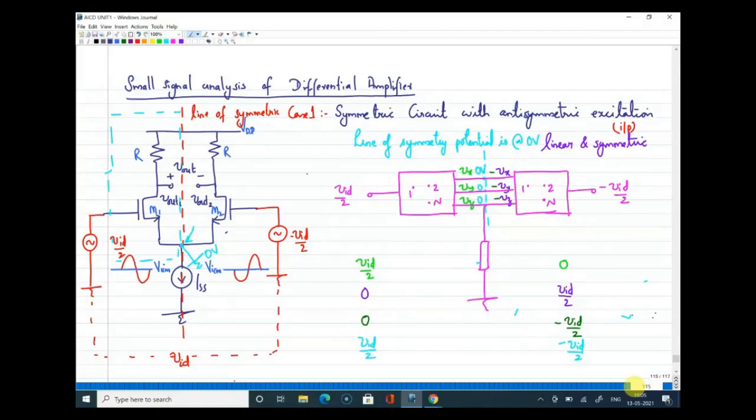All right, is it clear? So this is to everyone I am telling. Whenever we analyze small signal, we always say that DC voltages will be equal to zero. The meaning is the change in those voltages is zero. That is why we are marking it as zero, because a small signal circuit always represents devices or elements which have incremental changes.